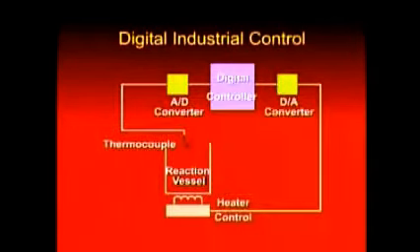So the temperature of the vessel is monitored to control the chemical reaction. As the temperature of the vessel rises, the heat has to be reduced by a proportional level. An electronic temperature sensor converts the temperature into an equivalent voltage value. The voltage value is continuous and proportional to the temperature. The voltage representing the temperature is converted into a digital representation, which is fed to a digital controller circuit. The circuit generates a digital value corresponding to the desired amount of heat. The digitized output representing the heat is converted back to a voltage value, which is continuous and is used to control a valve that regulates the heat.